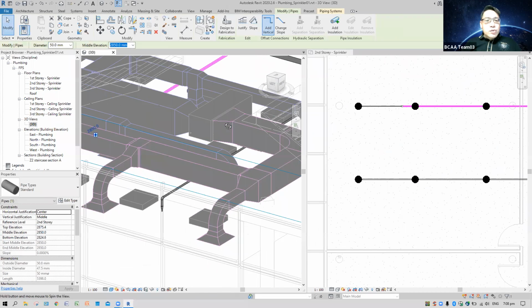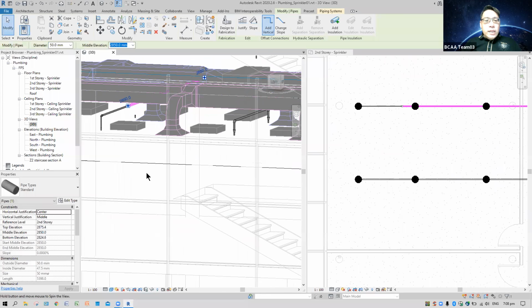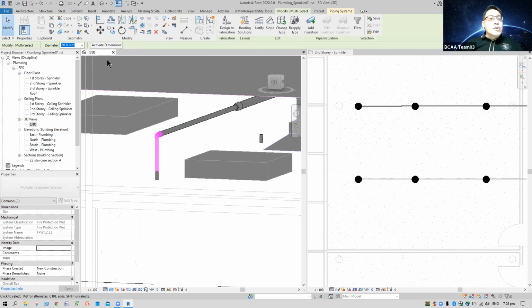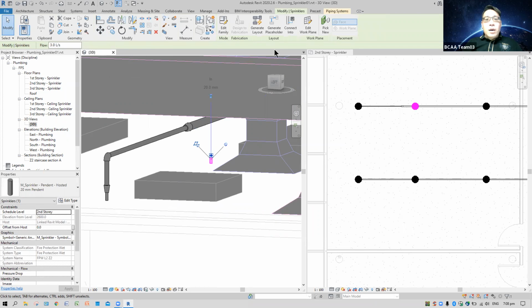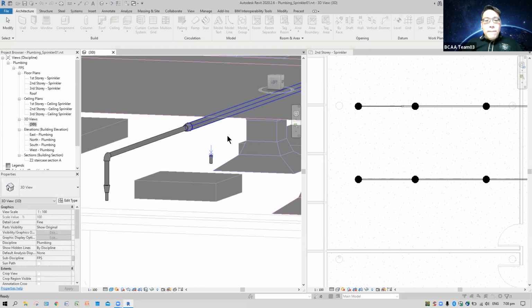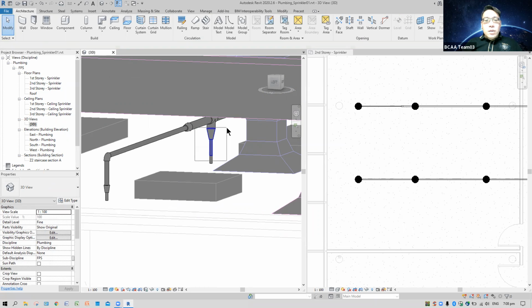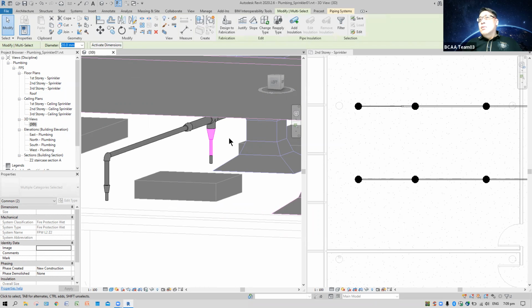Because you never know how you want to get it done here. So this portion here, I'll set it to 32 because your connecting pipe is 32. Same thing here. This is connecting up. Connect to, yeah. If you don't do it that way, you can draw it yourself also. But normally, as I say, drawing this in 3D is going to be difficult. You want to try? You can give it a try and see how. I tried until I gave up. Since the tool is so convenient, use connect into, then forget about drawing. It does it by itself, and then I just change my pipe.